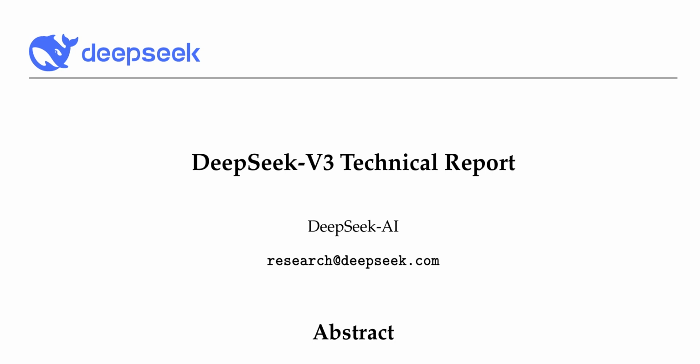Furthermore, to reduce application programming complexity, we aim for this hardware to unify the IB scale-out and NVLink scale-up networks from the perspective of the computation units. With this unified interface, computation units can easily accomplish operations such as read, write, multicast, and reduce across the entire IB-NVLink unified domain via submitting communication requests based on simple primitives.